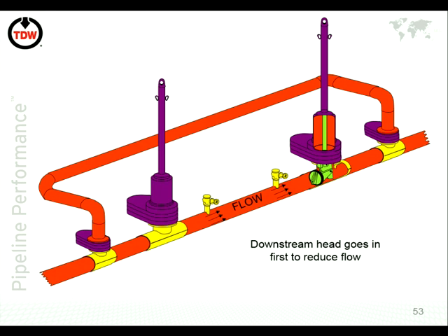Generally speaking, in the pipeline industry or in the fluid transportation industry, whether it be liquids or gas, ultimately flow has to continue. To stop flow, there's got to be no other way to do it. And typically when you get into the offshore side, that's what tends to happen. You have to stop the flow. But in the onshore market, there's more than one means of continuing flow, and a hot tap stopple bypass operation is one of them.